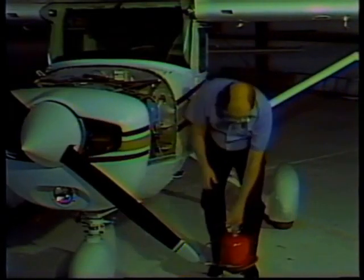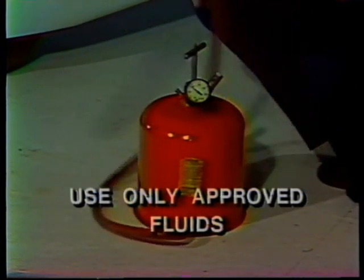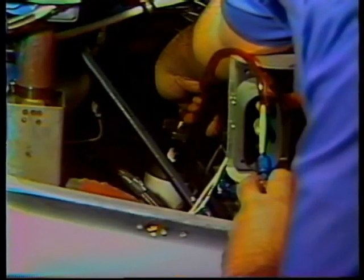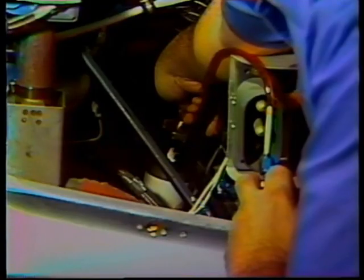Remove the filler plug and check the fluid level. If it's necessary to add fluid, be sure that you use the approved type as recommended by the aircraft manufacturer. If fluid must be added, fill the strut through the filler plug. Fill the strut to the level of the filler plug opening.